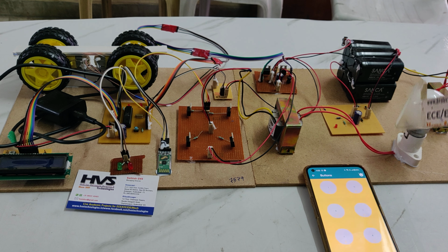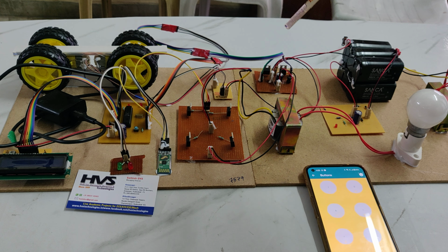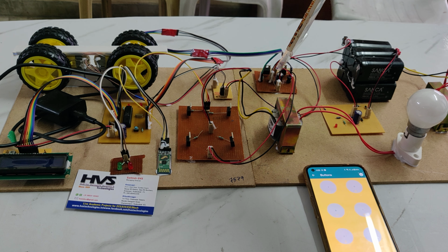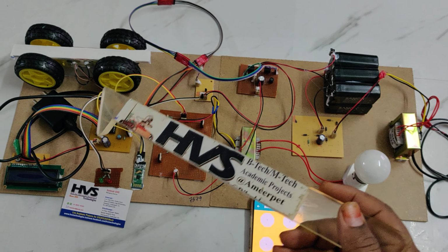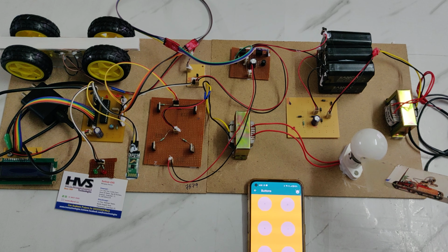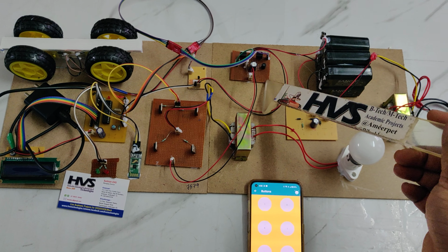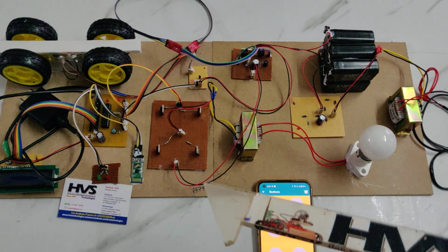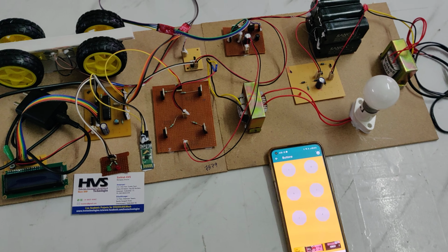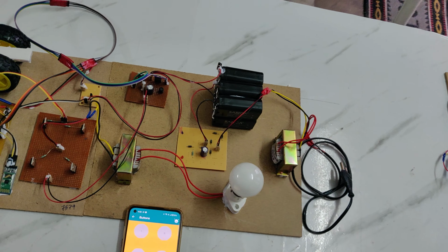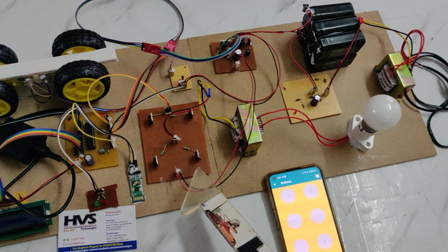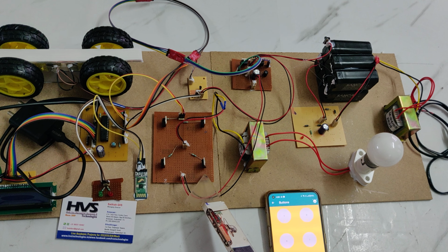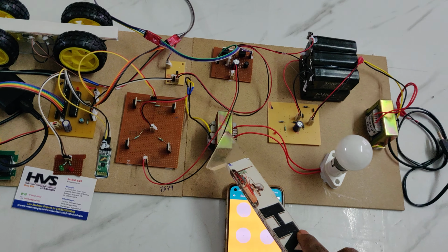Here the bulb represents a grid unit, and next the bidirectional converter is with the help of the MOSFETs. So this is the DC to DC converter along with the bidirectional converter. When we are providing the power supply from the battery to the vehicle section and again from vehicle to the grid section, in this manner it is used to convert the power between DC to DC, and DC to AC conversion will be achieved in our project. While we are converting DC to AC for the grid, this H-bridge is used to convert the DC to AC, that is the inverting circuit, and this one is the step up transformer.